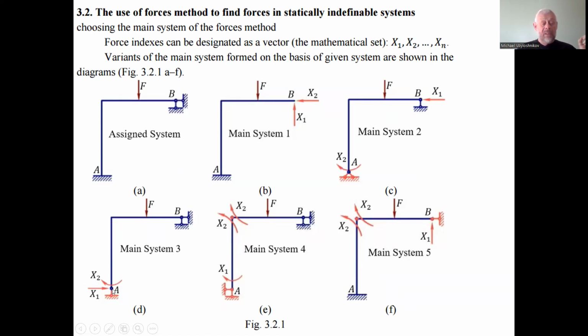So the sliding link provides in this case just only the vertical component of the resultant in the point A. So the unknowns remain the horizontal component in the sliding hinge, and the rotating moment in the embedding, x1 and x2, the horizontal component of the resultant force in the support A and the bending moment in this point A. Assume we would know these magnitudes x1 and x2?